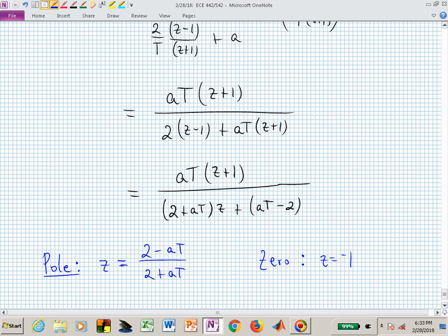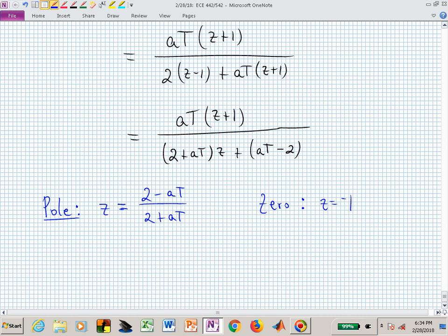But that's really fast, okay? That's as fast as we can go in our discrete time setting. If we put something in faster, what's going to happen? It's going to be aliased, and it's going to look like it's between DC and 50, even though it maybe is bigger than 50. So that's why we have to do anti-aliasing filters. But we haven't gotten there yet. But we do have a 0 at minus 1 in the z-plane.